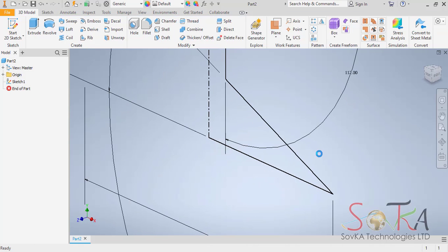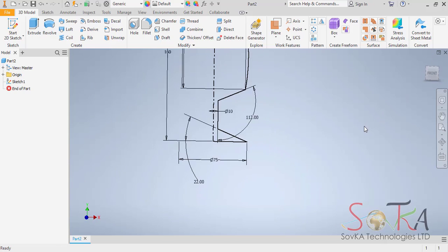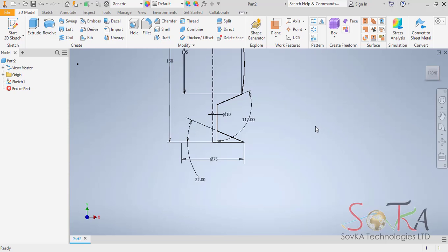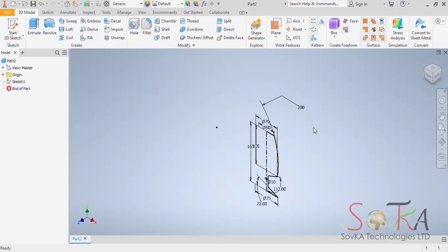It's very important to know, sometimes you can always use the go home tool along the view cube. It's good to know that F5 can take you to the previous view you were working on, and F6 can also always take you to isometric home.